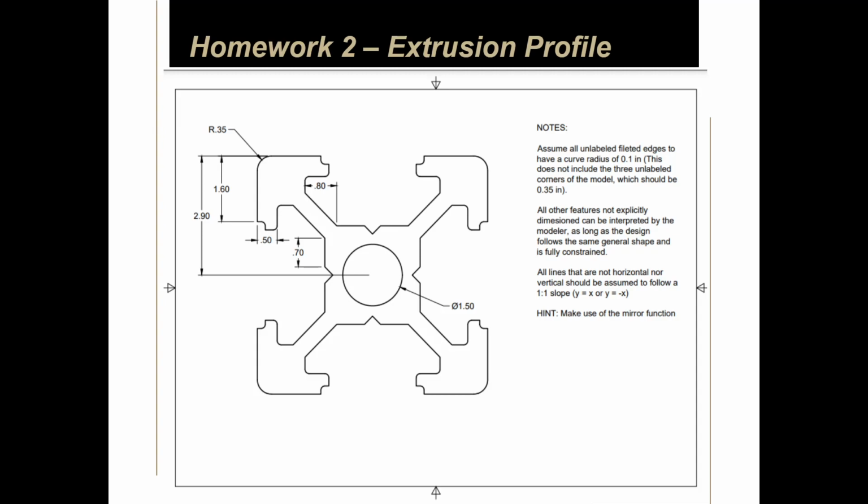But yeah, your homework for this week is to copy this sketch using dimensional and geometric constraints. Your goal is to limit the number of dimensional constraints and only use geometric constraints. The reason being that if you wanted to change it, you could change one number and it will change the whole sketch with it. I hope that makes sense, but when you create more complex parts, you're going to want to use more geometric constraints.